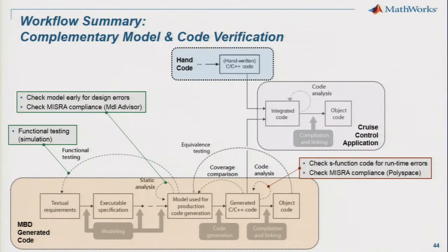That's correct. So then after that, I did the functional testing on that. We did show where we could do code coverage in the S function, so you get an idea how well that was tested, and then also the generated code, where you had more confidence that it was going to behave on your HIL bench the way you'd expect. That was actually pretty cool, where you could test the code without having hardware. So, yeah, virtually, right? Yep.